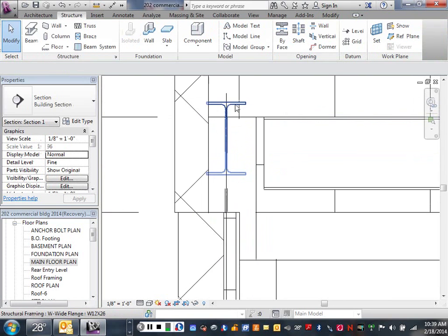So now the top of this beam that's running on the edge of my building is 2.5 inches taller than the beam that's supporting the bar joist. This one doesn't support any bar joist, it supports the decking. So the bar joist will sit on top of this beam and be 2.5 inches taller than the beam, and the decking will run straight across. Okay.